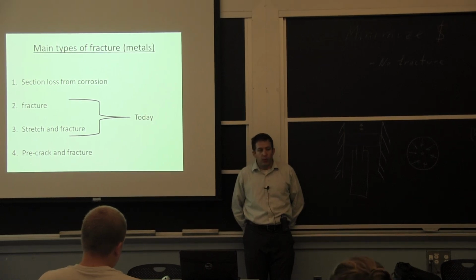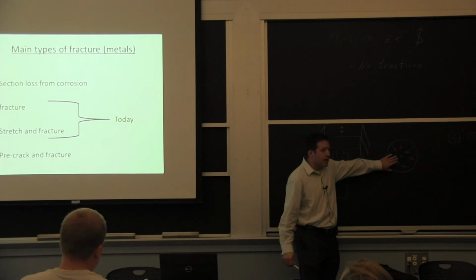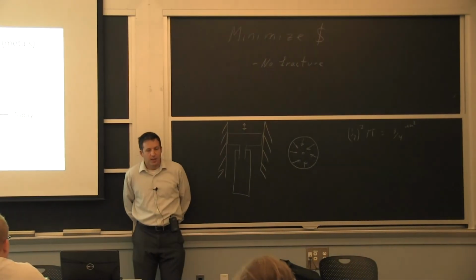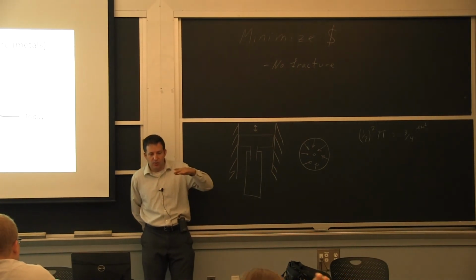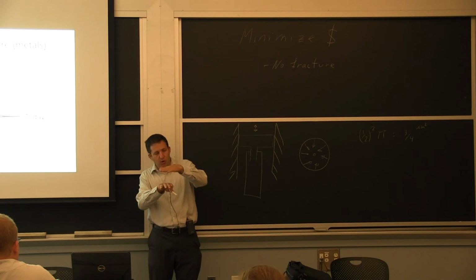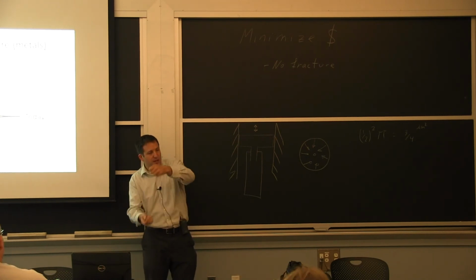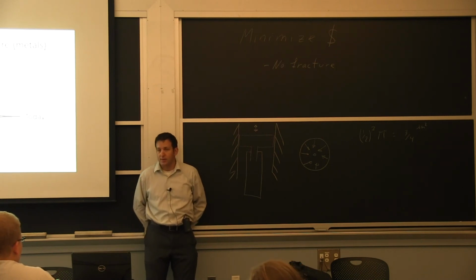Number of ways to look at it. For metals, you can see these leaves all around, how smooth it is. It really doesn't have any roughness to it. And what happens is as the crack continues from one cycle to the other, it just opens and closes and goes very slowly without pulling and stretching the material a whole lot. So that's why you don't have much roughness to that fracture.